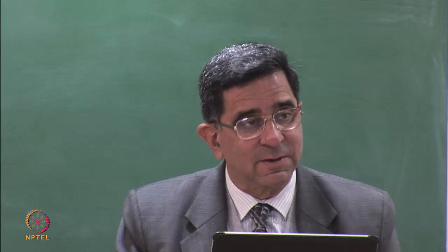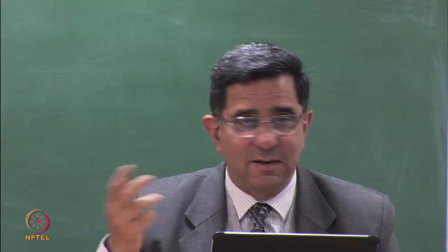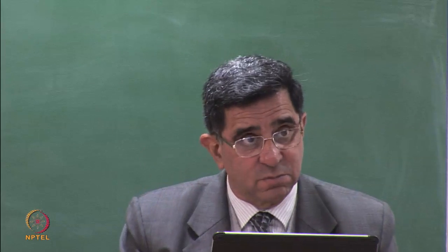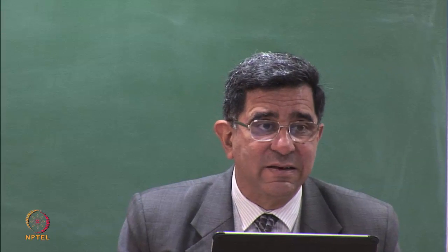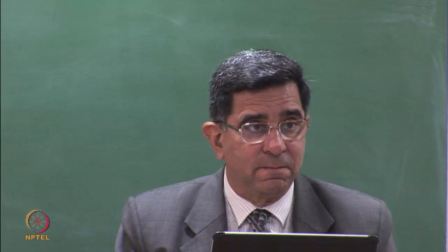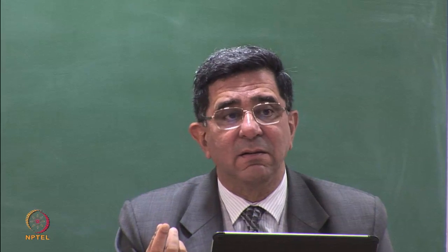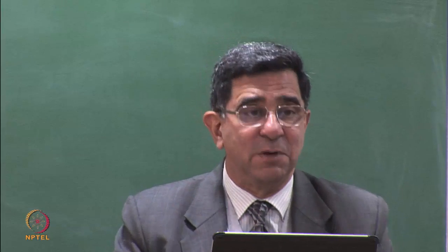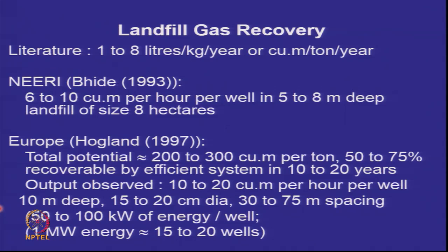We are attempting to take out the gas by covering these waste dumps and putting some wells in it. There have been 2 experiments, one in Gorai and one in Ghazipur in Delhi. The amount of gas which has come out has been 50% or less than what was estimated using the various models, as well as the gas extraction well tests. Before you put a set of wells, you do one well and you find out, are you getting this kind of output? Well, they got pretty good output, but what they didn't know was that over a period of time that output is not going to sustain, because that was the first well which was being drilled. Whereas these figures are coming from several wells in a well-designed landfill closed at the bottom.